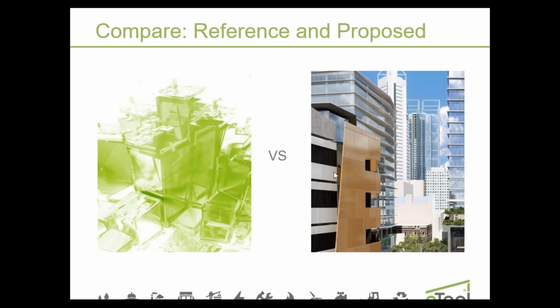Something we will compare against. So we normally compare to something that is just below 4 Green Star buildings in the same location with same parameters. So when you would use the software, you would need to conduct a benchmark model and then a proposed model to compare to each other.